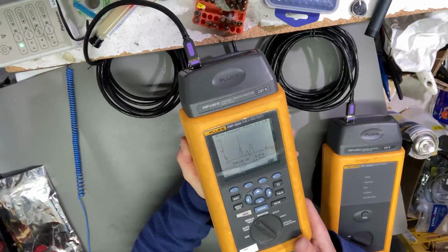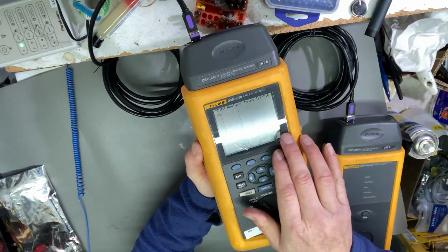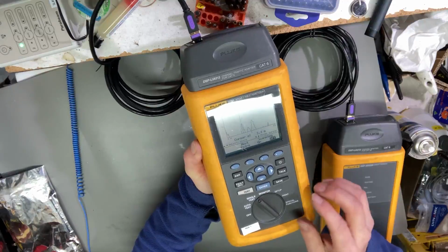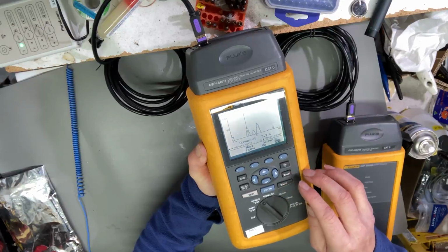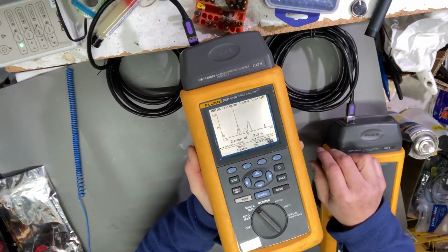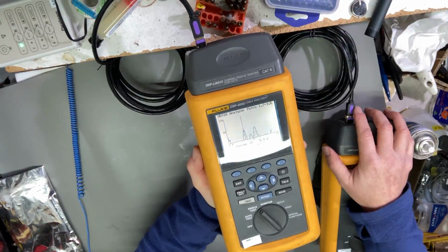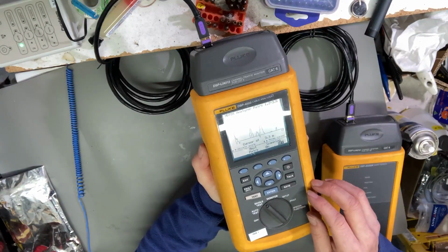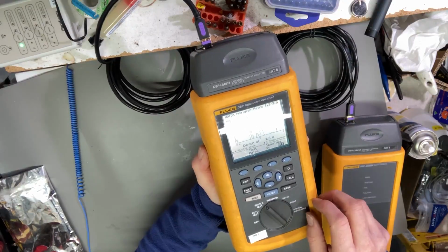This DSP4000 is like cable radar, with that horizontal line as a distance and the proportional reflection in the vertical axis. Let's have a look back at some other tests here. This also connects to a computer, and all these plots can be downloaded and stored and compared for later. So if your cable's starting to fail, go back in 6 months and you can compare it. You can just save that. You can set it up for different types of cable and different tests in the setup menu.